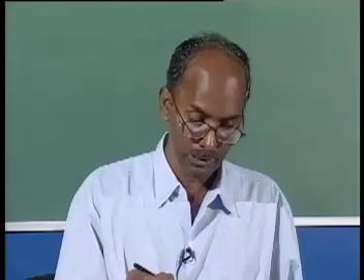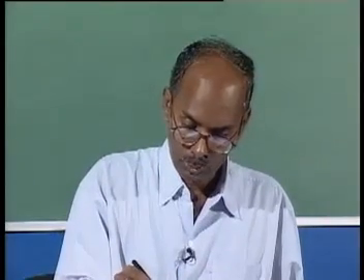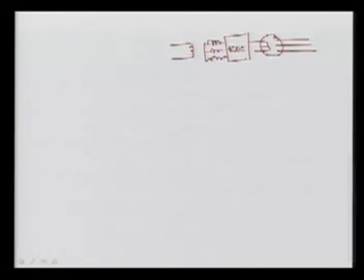What we normally do here, if I can model it again: this is your generator, from which we take the 3-phase power, and this is your field winding. This field winding is basically coming through your exciter, and this exciter is nothing but a 3-phase power generator, another alternator, and the field to this we give through your amplifier. If you remember, this was nothing but your change in VR here, and this field goes to your generator or alternator, where the 3-phase power supply goes.